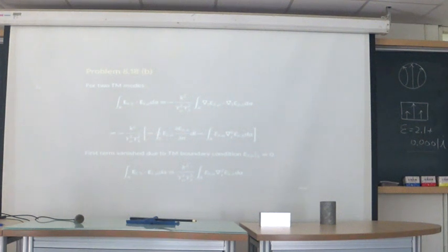So for two TM modes, the inner product of the transverse electric field is equal to this. And again, we use Green's identity and Green's theorem. We can find that the first term will vanish because of the TM mode boundary condition, because our E is proportional to the psi.